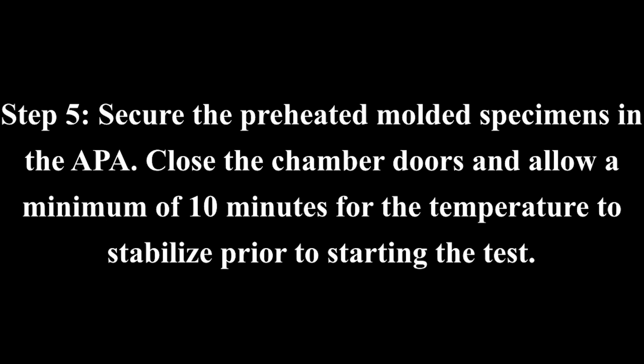Step 5. We need to secure the preheated molded specimen into the APA machine. We need to close the chamber doors and allow a minimum of 10 minutes for the temperature to stabilize prior to starting the test.